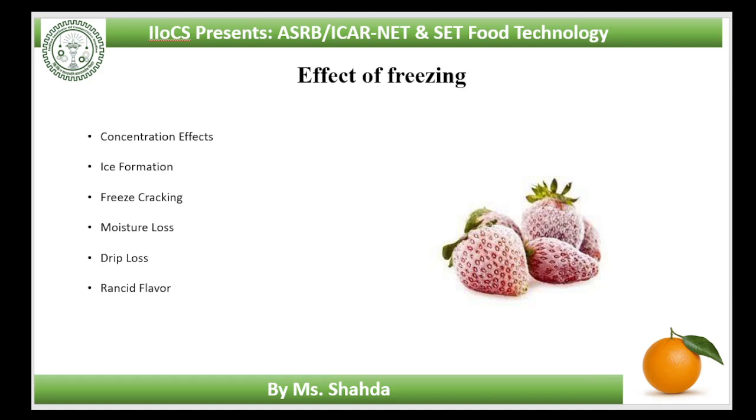The main effect of freezing on food quality is damage caused to cells by ice crystal growth. Food emulsions can be destabilized by freezing, and proteins are sometimes precipitated from solution. Meats have a more flexible fibrous structure which separates during freezing instead of breaking, and the texture is not seriously damaged. In fruits and vegetables, the more rigid cell structure may be damaged by ice crystals. The extent of damage depends on the size of the crystals and hence on the rate of heat transfer.